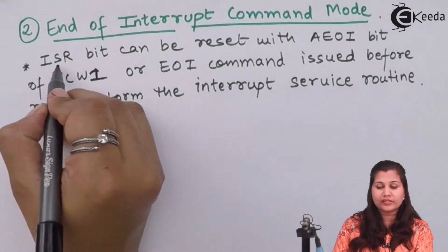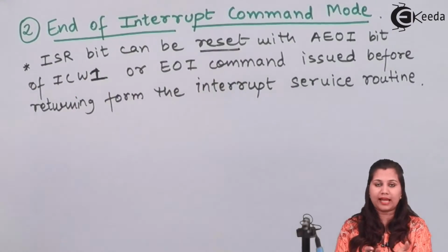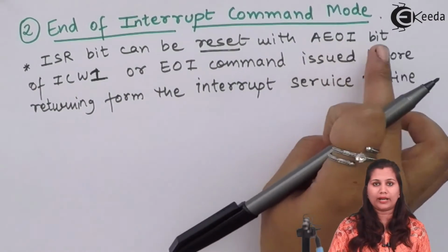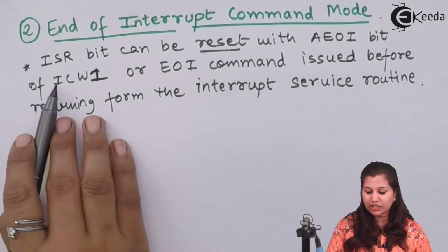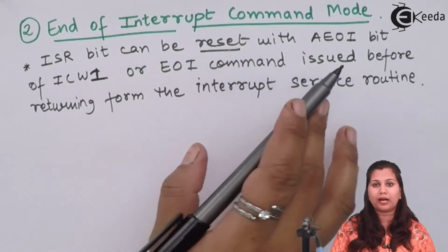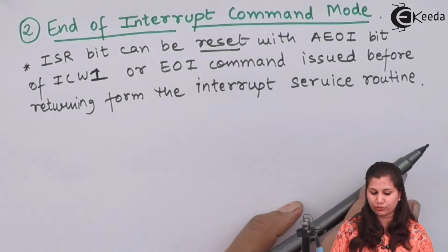The in-service register, that is the ISR bit, can be reset, meaning its value can become 0, with the AEOI, that is the automatic end of interrupt bit of the initialization command word first, or the end of interrupt command which is issued before returning from the interrupt service routine.